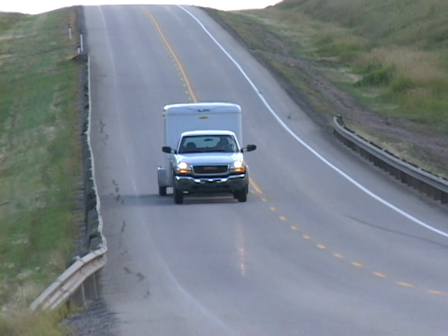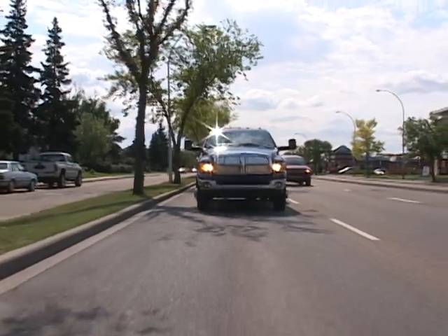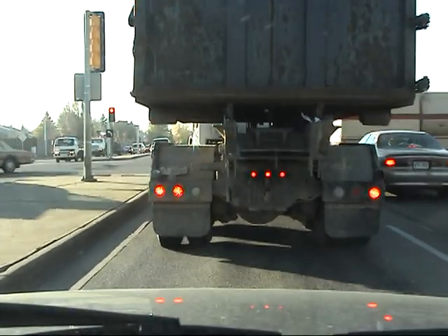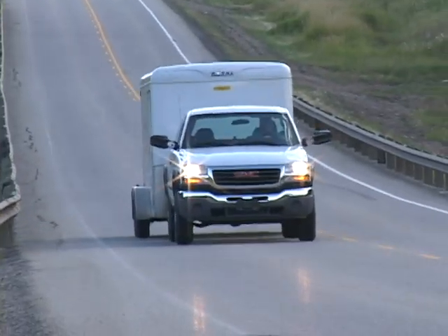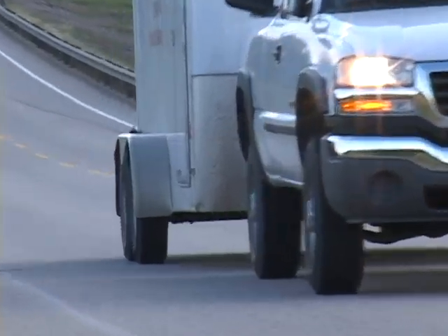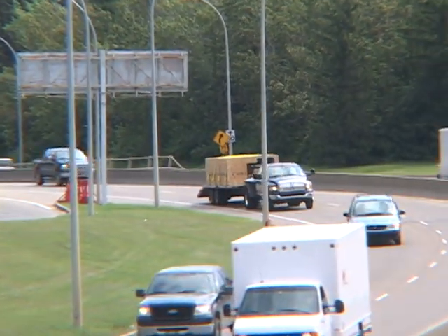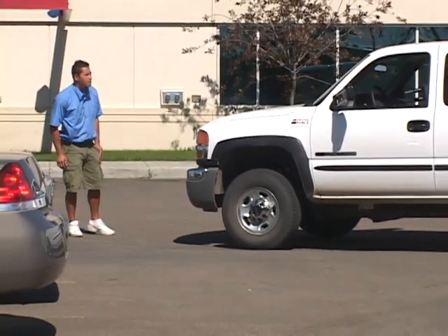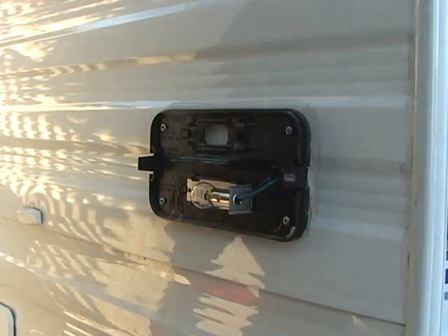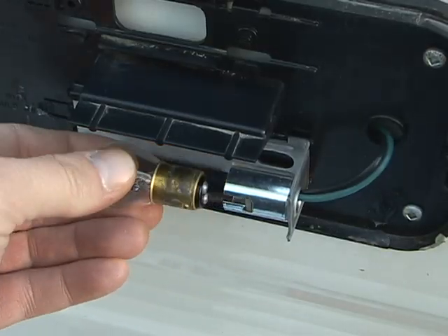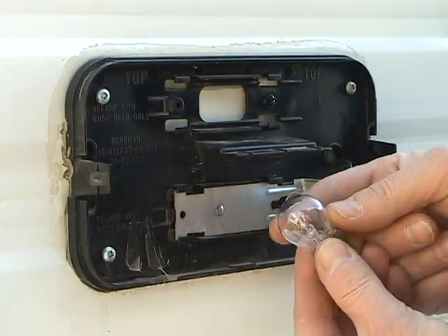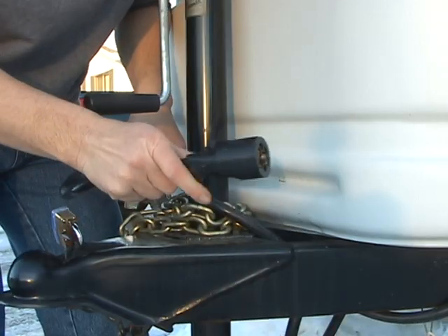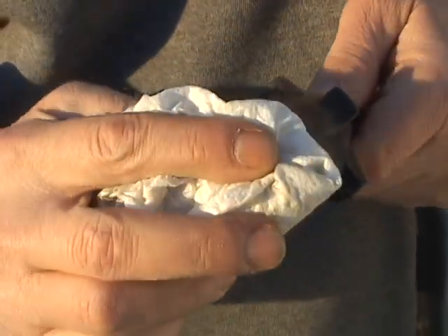When operating a vehicle-trailer combination, headlights, turn signals, side and height marker lights, and brake and hazard lights must be functioning reliably. Because of the trailer size and limited visibility for both the driver and other vehicles around you, it is imperative you check all lights regularly. Also, check wiring for wear and make sure that light bulb sockets and ground connections are clean and shielded from moisture. Regularly clean out the main plug to be sure of a good contact of all the pins.